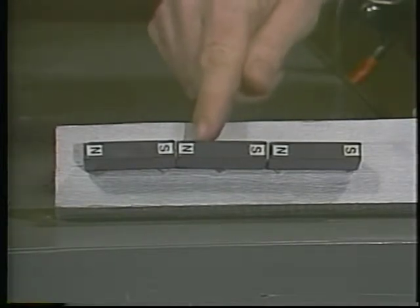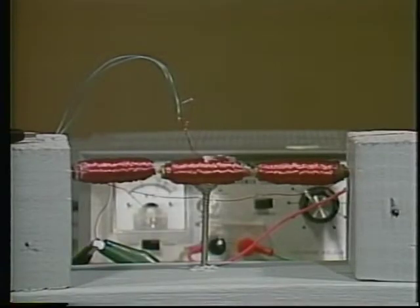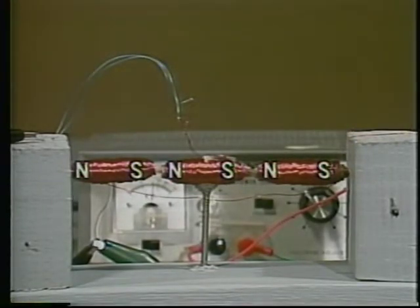In order to keep generating torque, we must provide a way to keep the rotor turning. The only way to do that is to reverse the poles on either the rotor magnet or the stationary stator magnets just as the poles are lining up. The rotor magnet would then be pushed and pulled around another half turn. We can accomplish this if we replace our permanent stator magnets or rotor magnets or both with electromagnets.